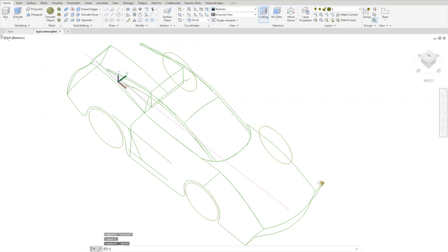Okay, so we demonstrated how to generate lines by selecting the edge surf command, and then I just demonstrated how to mirror it from one side to the other side, because the entire car is symmetrical, and I suggest you do the same. And then later on, as we create, for example, glass areas and windows, we're going to just simply apply a semi-transparent material. So the RMAT, rendering materials, command will enable you to select certain materials, transparent materials.